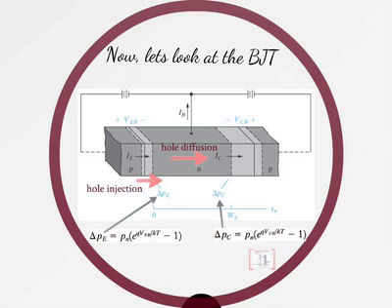So it's easy to get confused, but if you're ever confused, just go back and look at the junction. Remember, the collector to base junction must be reverse biased for normal operation. The emitter to base junction must be forward biased for normal operation. Once you keep that picture in mind, everything else can be surmised logically. You don't need to memorize anything. I want you to be able to do that sort of logic. Fairly straightforward, right? Once you do it a few times.